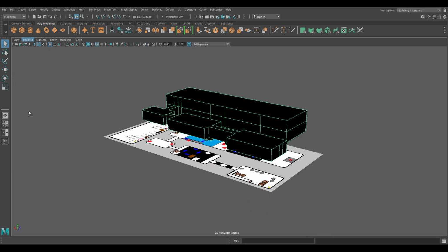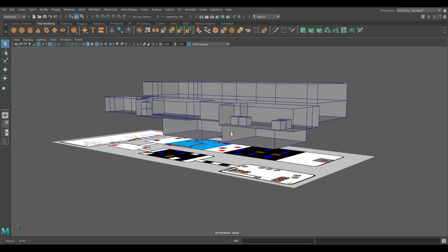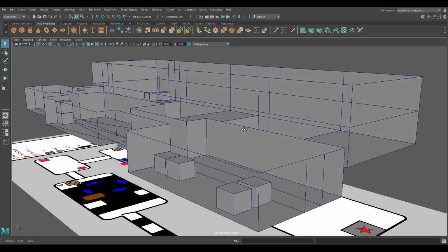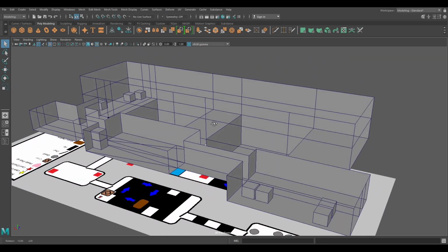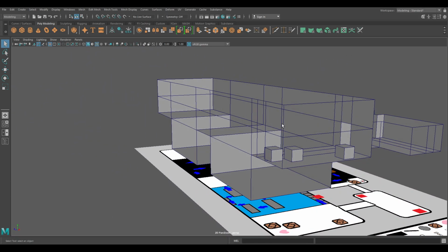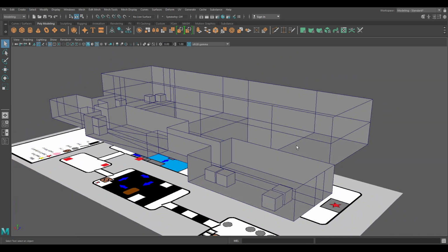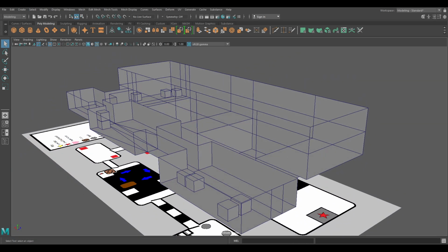Now, if I turn on my Backface Culling, you can see that I've populated it with a couple of assets, and I have made it out of only thin, one-sided geometry. Obviously, if I was making this into a proper game, where we would travel from indoors to outdoors, I'd more than likely make my walls double thickness and include some windows and doors. But for now it's just an indoor level, so I can build it, get it in Unreal, and test it out.